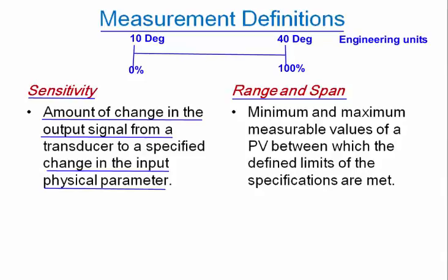And we need to know what those engineering units are. But when we discuss the range of the instrument in terms of its percentage deflection, then we talk about normalized range. Because once we've decided what the engineering units represent, we can use the normalized range, for example, 4 to 20 milliamps, or it could be 0.2 to 1 bar pressure.